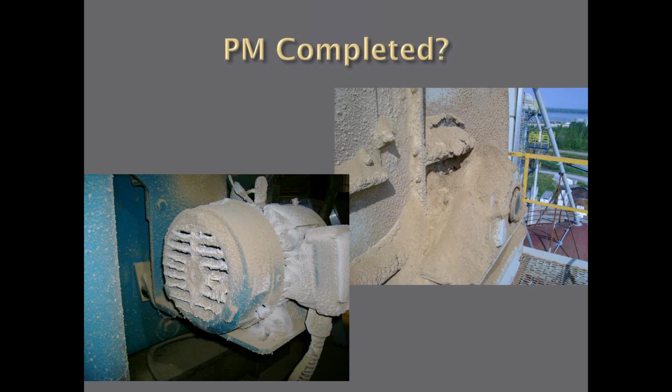So what I did, I took a temperature on the front bearing of this motor, and then I had the operator and maintenance person actually clean everything off the fan guard. We scraped all the crud and dirt off the motor. We cleaned it up really good. And then I retook the temperature on the front bearing. The front bearing temp on this motor went down 35 degrees F.